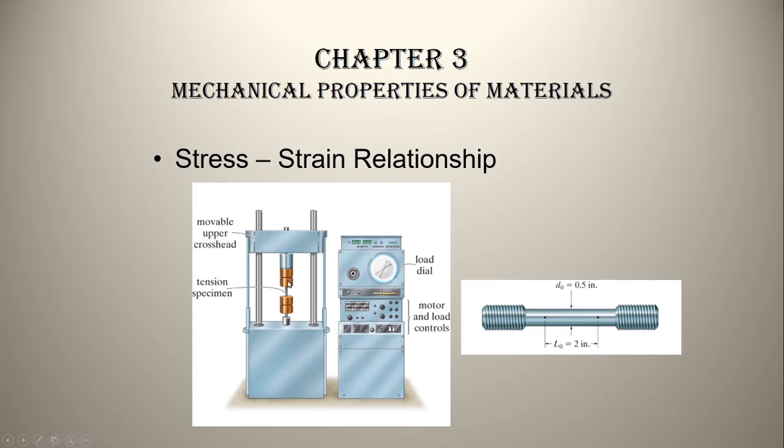As you apply the load, you will note that there's a strain, and this is the load dial, you can read there. And similarly, the computer will be telling you directly what is the stress and what is the strain. So you can directly read stress and strain for an applied load. This is how you find the stress and strain relationship. And as I said, that relationship looks something like this.